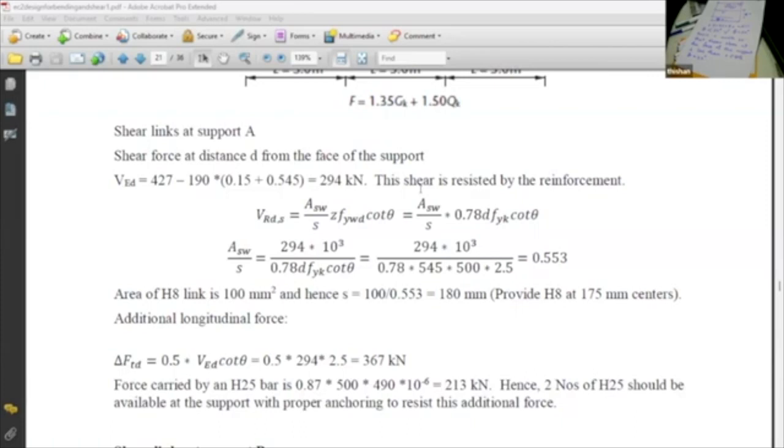Anyway, when I cover the foundation designs, I will show you how to use it. The same equations will be used over and over again. But you can see for flexure, I have given a simplified method, or you can use the equations. For shear, I have again given a very simplified method so that you can use one equation, forgetting about all the complications that are being created. And still our designs will be optimum because I don't like shear governed designs. I always like flexure governed designs.